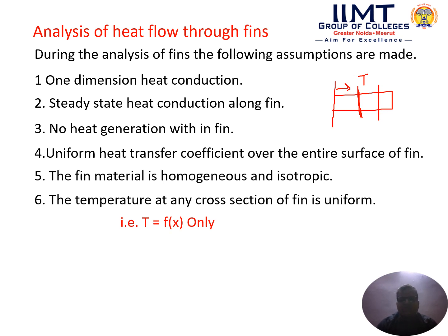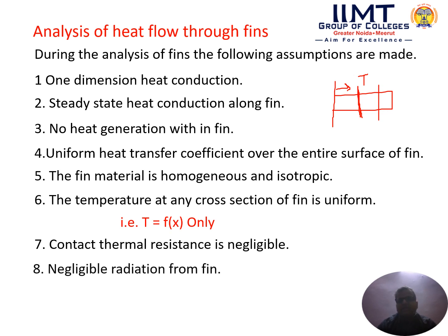Next one is the thermal contact resistance is negligible, and the last one is the heat transfer by radiation is neglected. These are the 8 assumptions which we have to take for the analysis of heat flow through the fin.